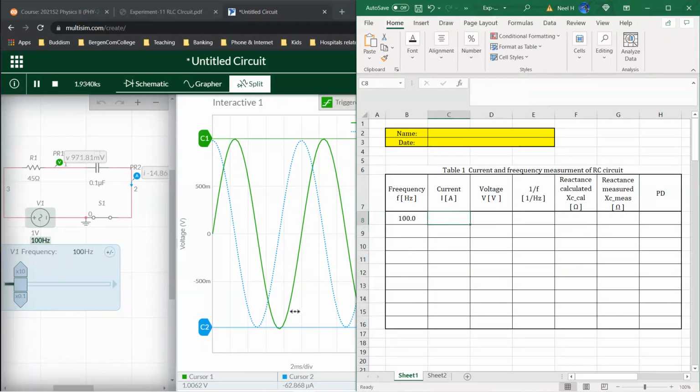Okay, the current I'm measuring, doesn't matter, I measure the negative side, but we're interested in the magnitude. 62.868 equals 62.868 times 10 to the power minus 6. It is micro. And then it will auto adjust to the scientific notation. If not, make sure you put this into scientific notation. And that should show all the measurable decimals. In this case, we are measuring 5 significant figures, so I should readjust this to show all the significant figures.